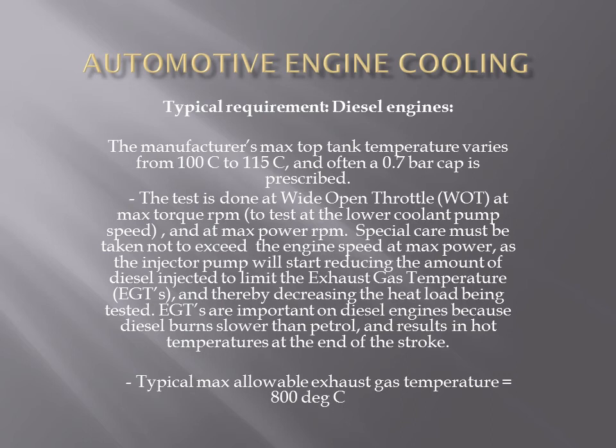Special care must be taken not to exceed the engine speed at maximum power, as the injector pump will start reducing the amount of diesel injected to limit the exhaust gas temperature, or EGTs, and thereby decreasing the heat load being tested. EGTs are important on diesel engines because diesel burns slower than petrol and results in hot temperature at the end of the stroke. Typical maximum allowable exhaust gas temperature equals 800 degrees.